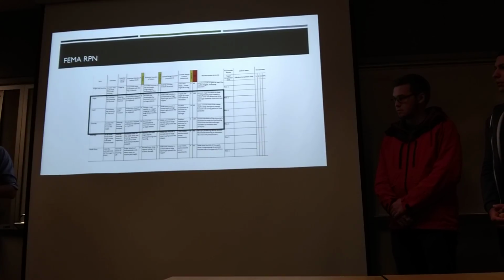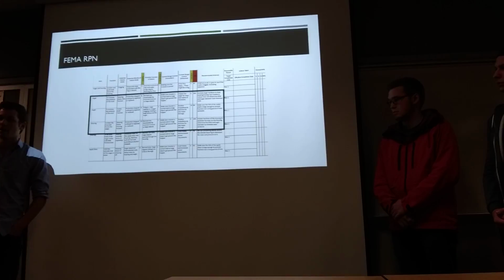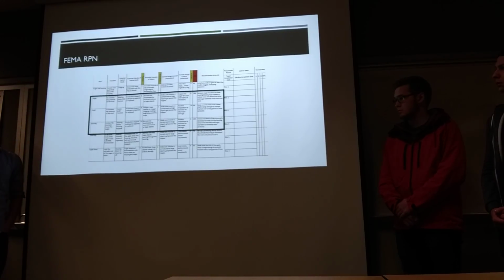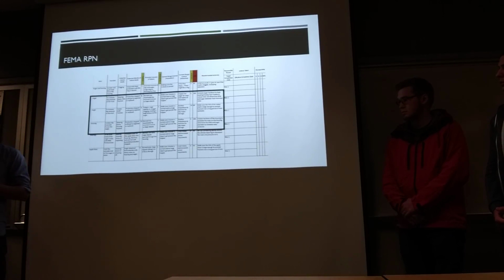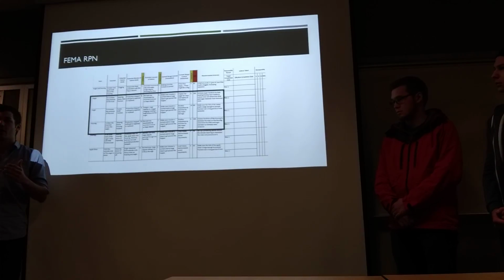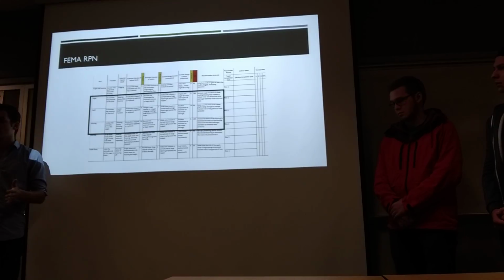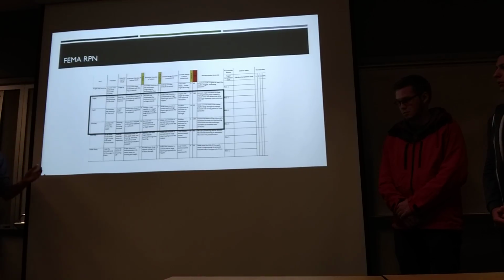The way that we address that is we look at material that is corrosion resistant, and we have thick enough material so that it can withstand quite a bit of cyclical stress and maximum stress. Finally, on our housing, because we are pressurizing, we want to make sure that our housing has adequate hoop stress within the thickness of the barrel, as I was calling it earlier, to make sure that it doesn't crack. If that cracks, then the whole machine has to be disassembled and reassembled with a completely new barrel, taking time and money. So those are our three concerns that we are working to address.